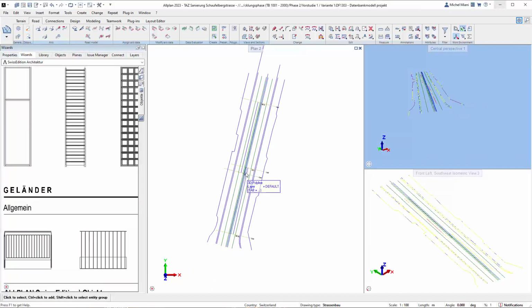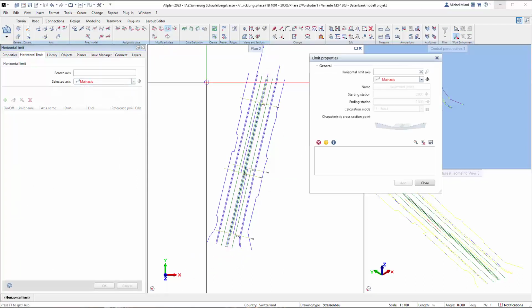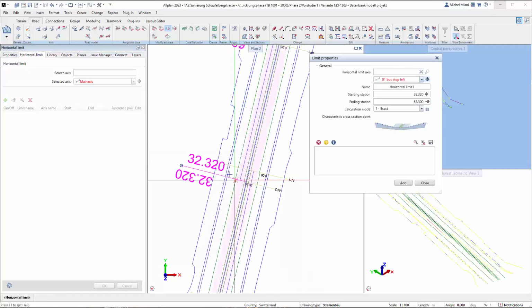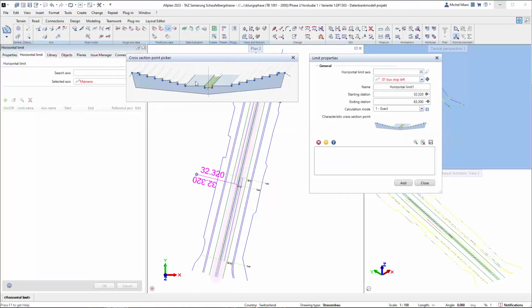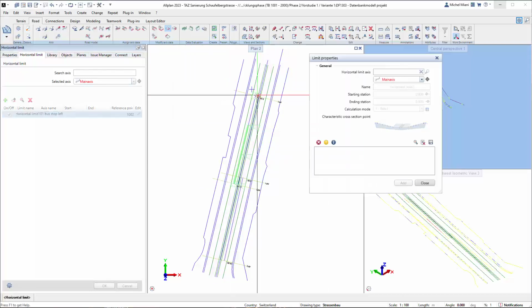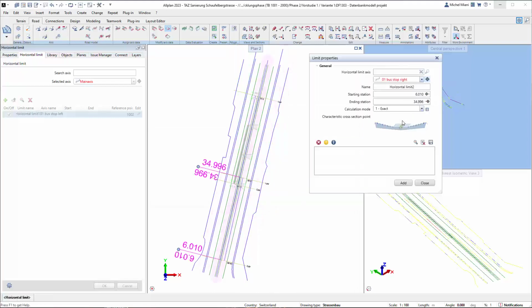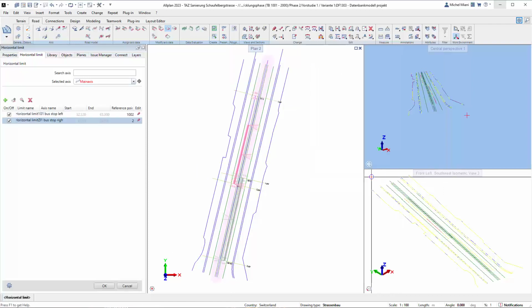After assigning the parameters, I set the width horizontally using the limits function. To do this, I select the main axis, click on the green plus in the palette, then I specify an axis to which the lane must adhere. By means of the picker, I can select the axis. I check the stationing and select the characteristic point. After that, I go through limits for limits. When naming the axis, I decided in advance at which characteristic point it should be.